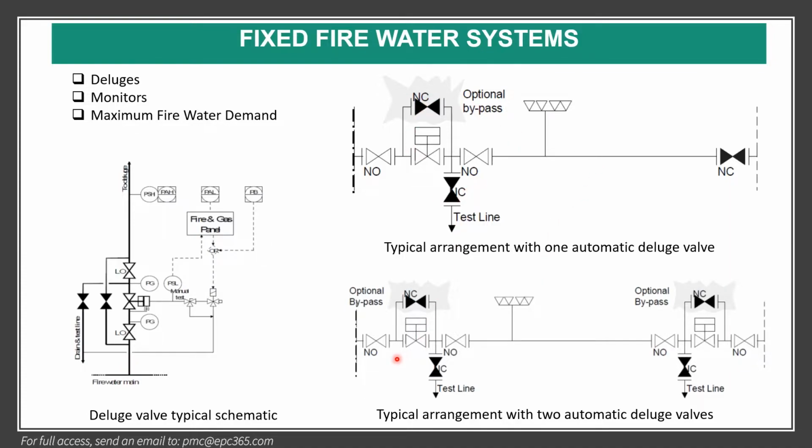There are certain installations we put to the deluge system and not manual, but this deluge valve skid normally should be at least 15 meters from the protected area to be safe. So there are certain things about the configuration, how it will be working, and we will discuss it in our workshop when we see each other.